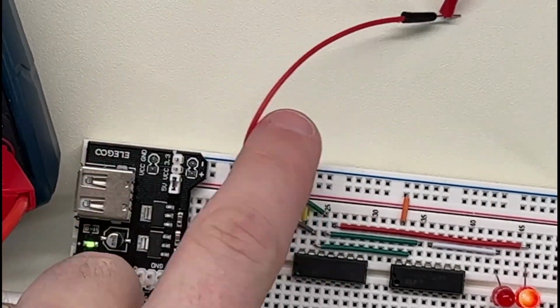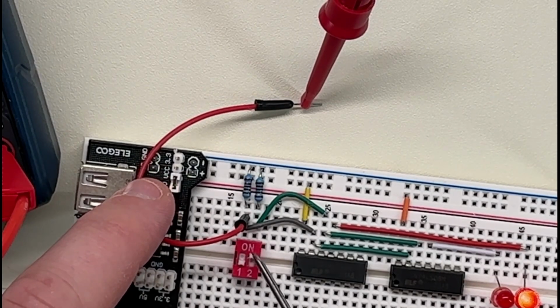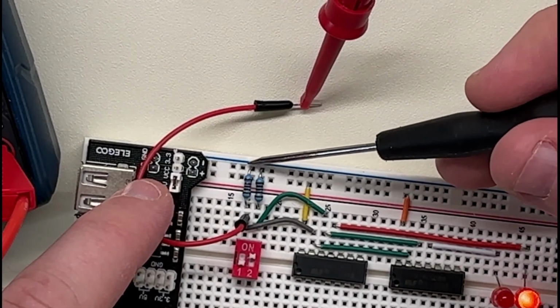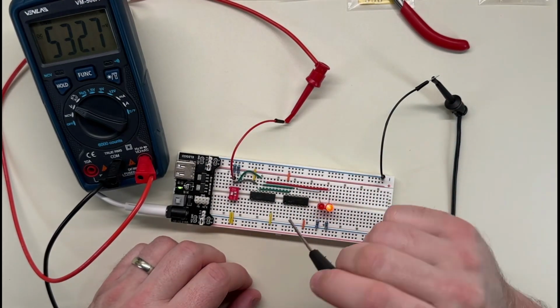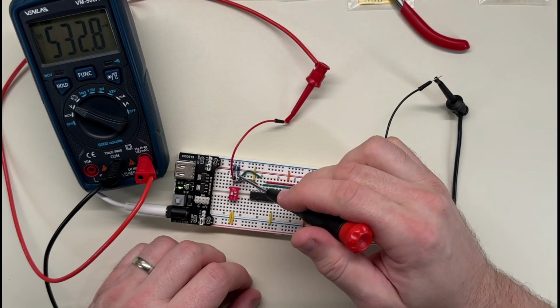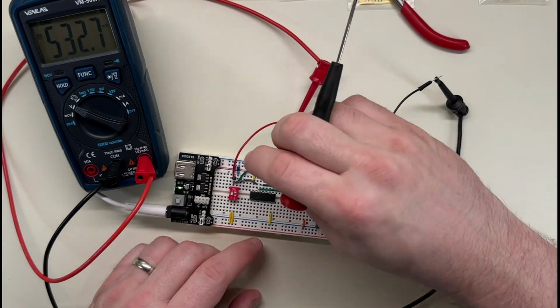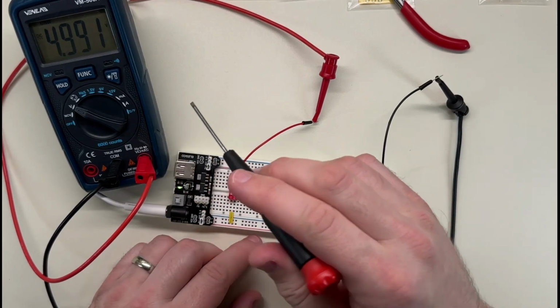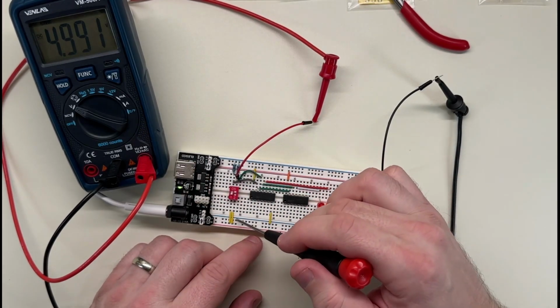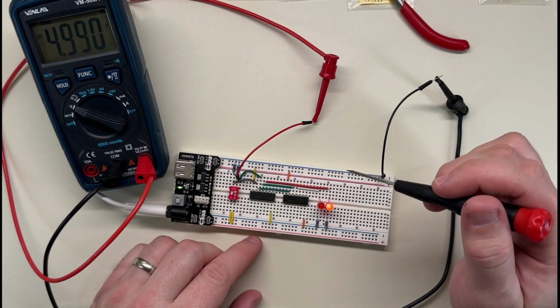Okay, we can't see the multimeter now, but we can see the resistors. This resistor is connected to this switch, and this resistor is connected to this switch, and these are the pull down resistors I was talking about. You see they connect to minus here. So there's 532-ish millivolts between ground and the other side of this pull down resistor. So it's a very small amount of voltage. But if we go to the other switch, the one that's on, we're getting close to 5 because it's not going through here at all. Well, maybe a tiny amount is, but it's pretty much coming straight from plus.